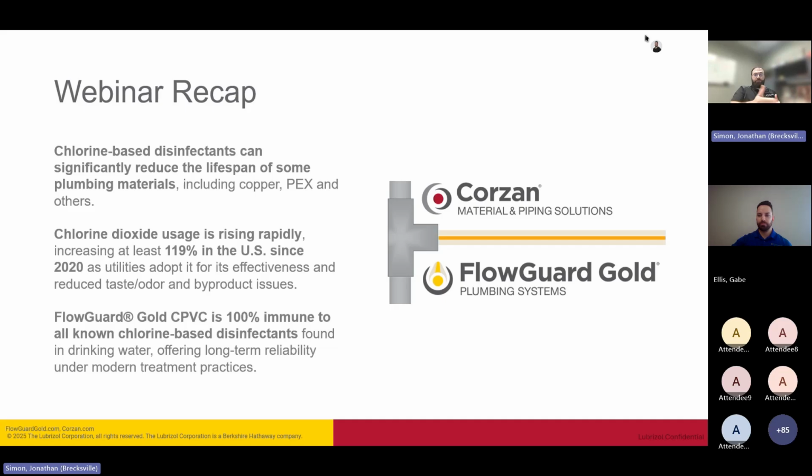I have seen, Gabe gave the example in Hamilton, Ohio, a cold water HDPE main that actually failed in a relatively fast time frame relative to its expected life. That was cold water, wasn't even operating at extremely high temperatures or high pressures for the system, but because it had chlorine dioxide in it, it was just such a highly aggressive water chemistry that we saw those failures.